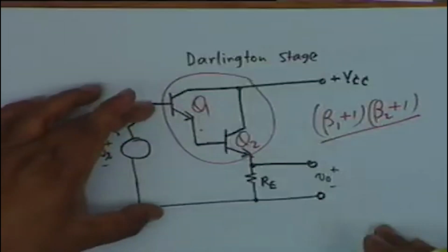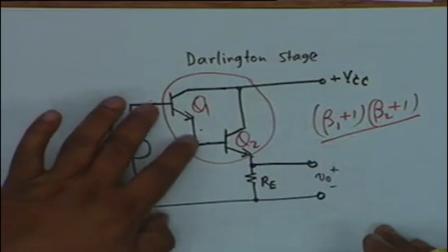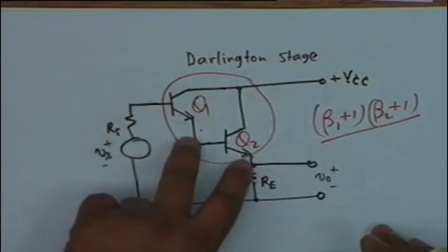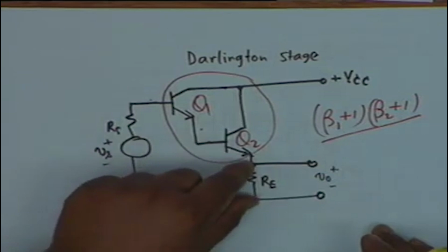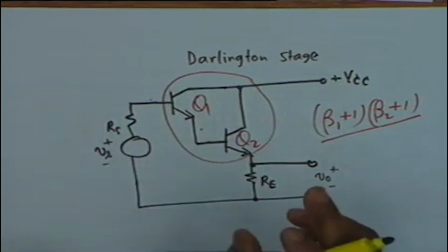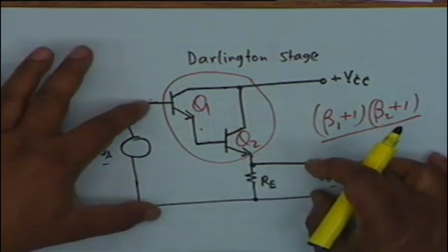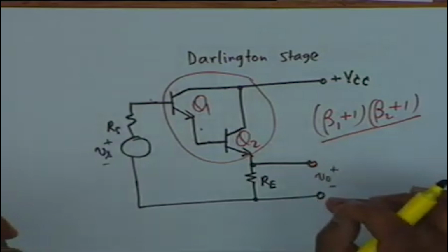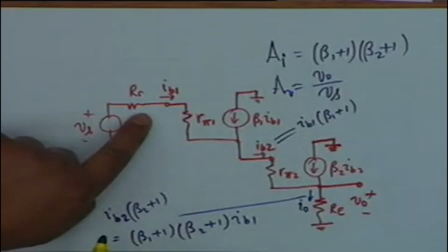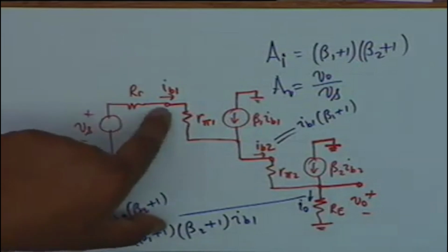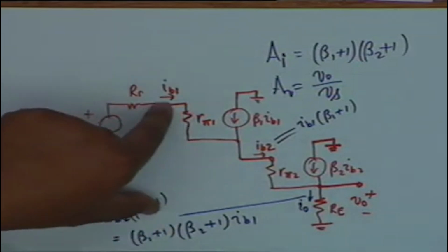If you look at this circuit, you see this voltage minus VBE1 minus VBE2 is this voltage, and for AC this voltage should be exactly equal to the AC of this voltage, which means that the voltage gain should be equal to 1, but because of RS the voltage gain is slightly less than 1, because what you apply here is not Vs, it is slightly less than 1.